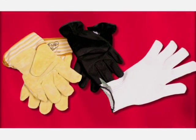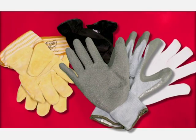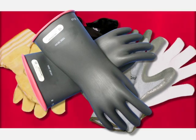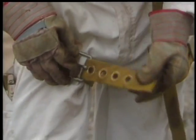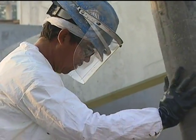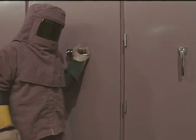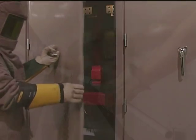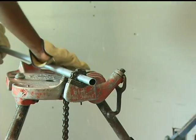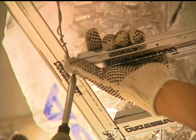These include gloves made of leather, canvas or metal mesh, fabric and rubber-coated gloves, and voltage-rated gloves. When selecting gloves, use gloves specifically designed for the hazards and the task. For example, wear heavy-duty rubber gloves for concrete work, welding gloves for welding, and insulated gloves and sleeves when exposed to electrical hazards. Remember, gloves designed for one function may not protect against a different function, even though they may appear to be an appropriate protective device.